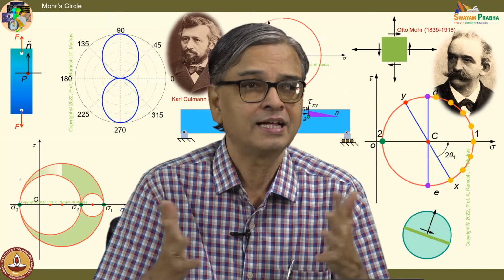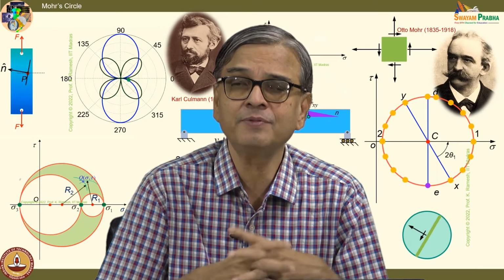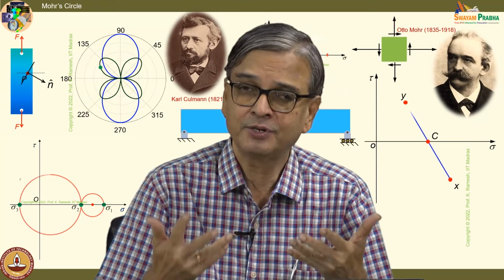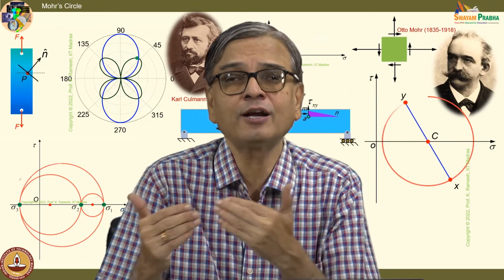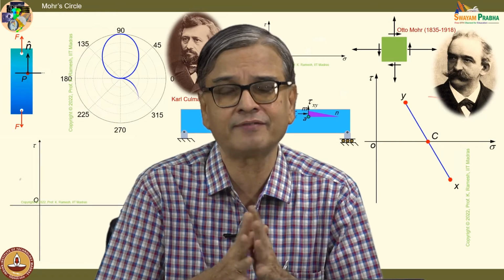Fine, by linear superposition, I can add the stress tensor. From the final stress tensor that I have got, I can find out the principal stresses and go back to theories of failure, and a number of theories of failure that people have developed.